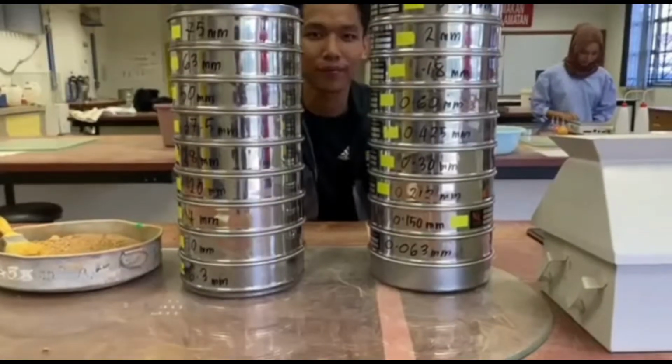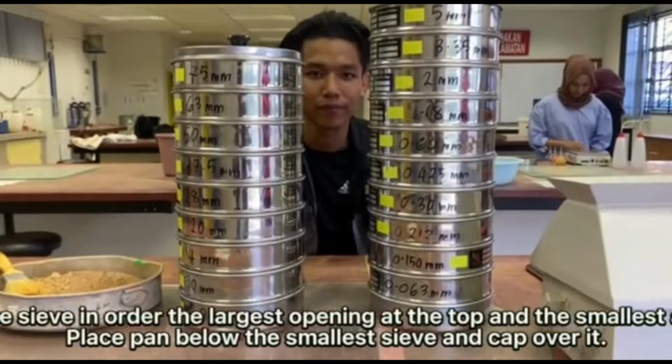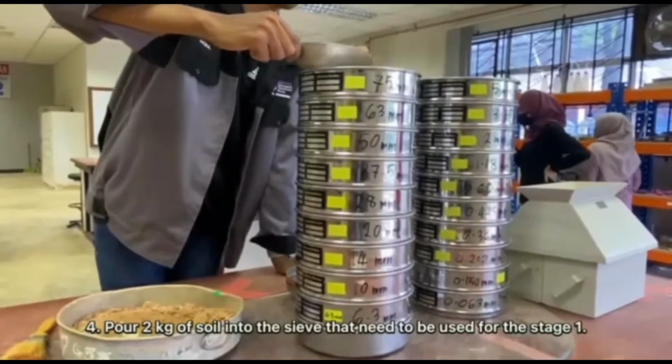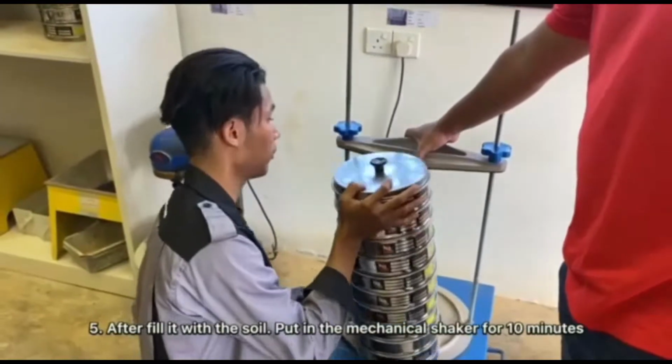Next, we need to arrange the sieve in order, the largest opening at the top and the smallest at the bottom, and then place the pan below the smallest sieve and the cap over it. Next, pour 2 kg of soil into the sieve that needs to be used in stage 1, and then after filling it with the soil, put it in the mechanical shaker for 10 minutes.